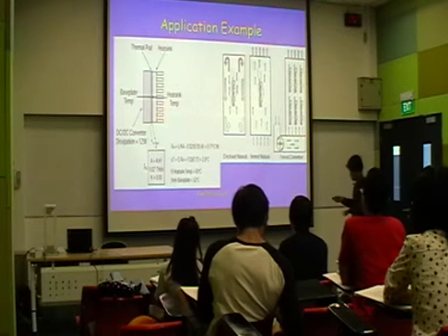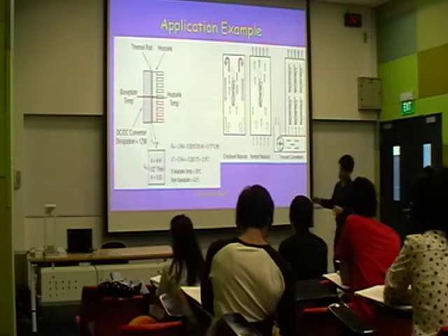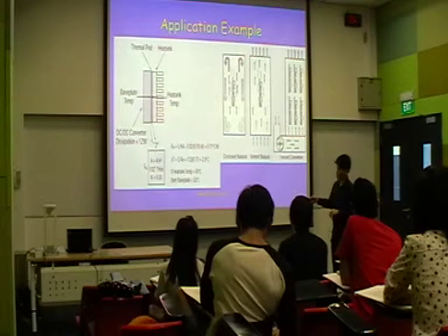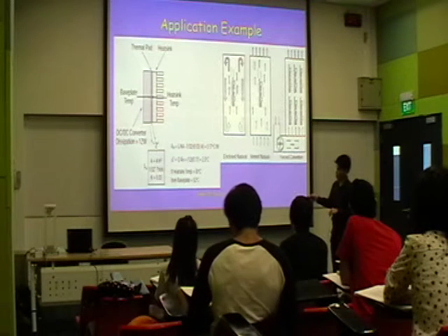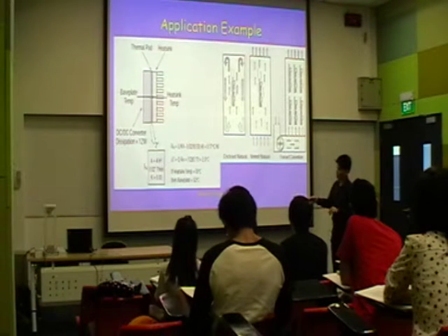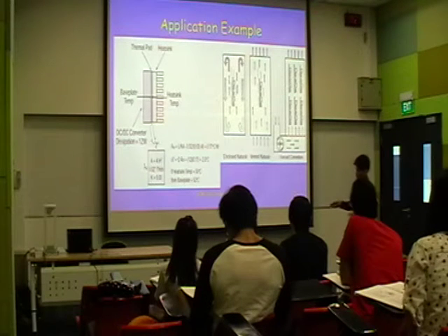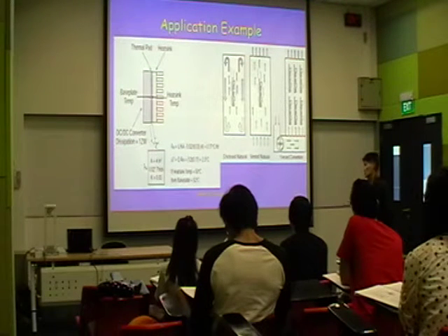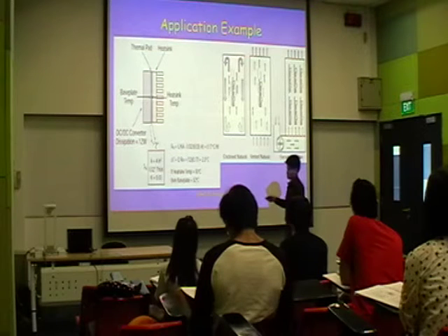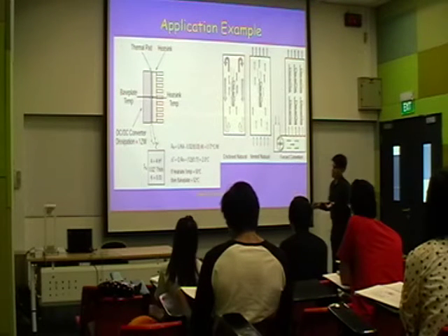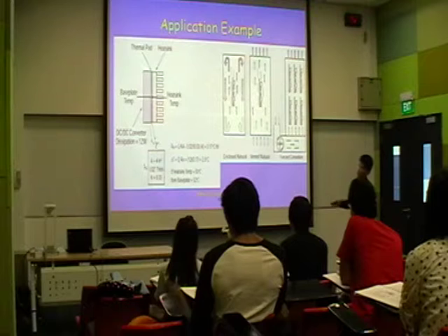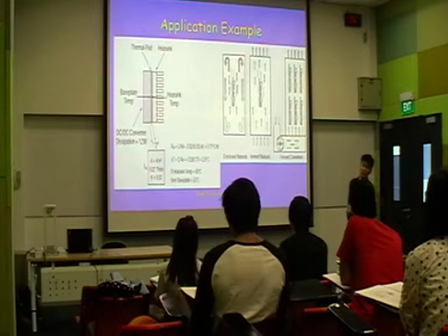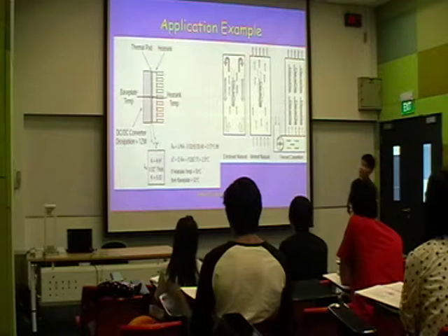So you just imagine if the surface area of the heat sink is wider, you will definitely get much more. The A here, R will be lower. Okay, no, sorry, A is wider, so you will expect R to be smaller. So if R is smaller, that will cause the change in temperature to be smaller. So it's not only A, you also have to depend on the thermal conductivity of the material that you choose. Right? There's a standard table that you choose from.